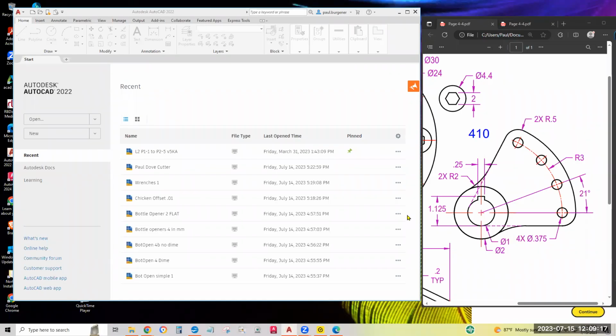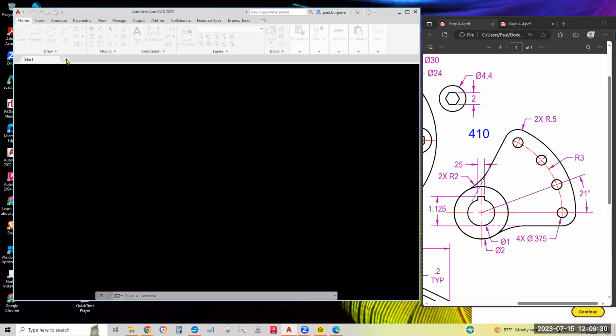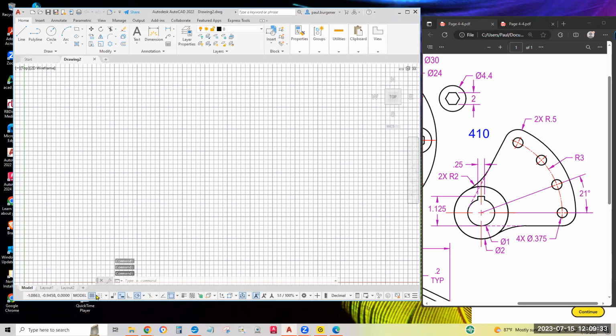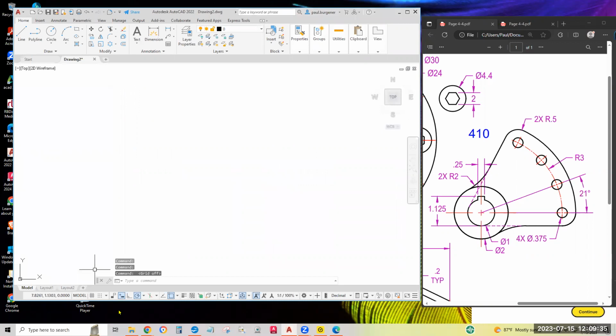This tutorial shows how to do exercise 4-10 on page 4-4 of the introductory handout of the Shipyard Night School program. You start a brand new drawing. Turn off the grid. Turn off these. Double check I got the 5 O snaps. Yep. Double check I got polar tracking set for 90. 45 will work. And I'm using dynamic input.